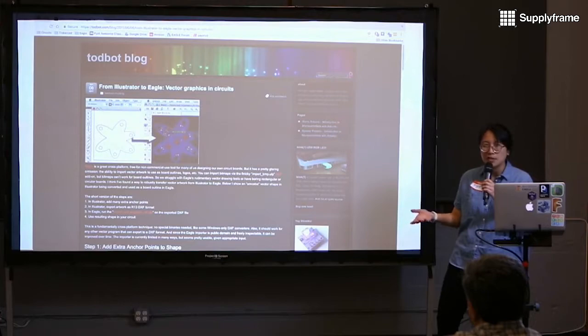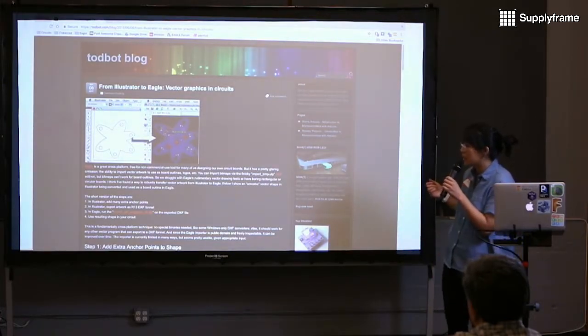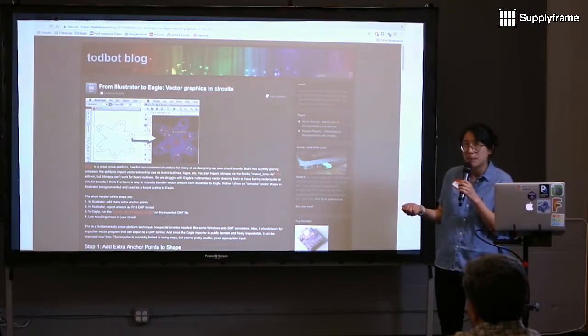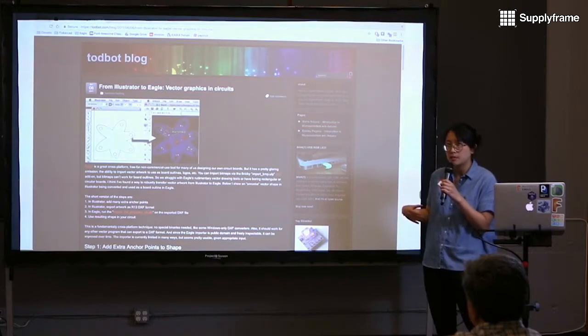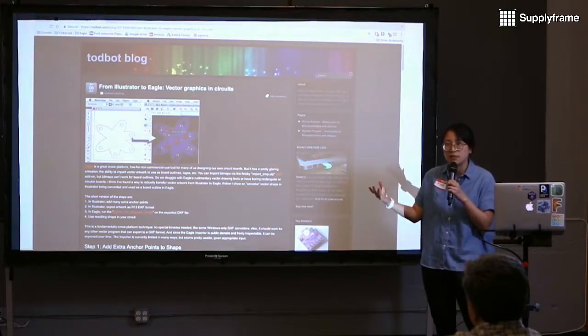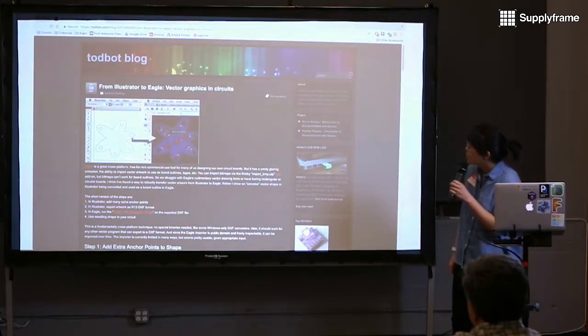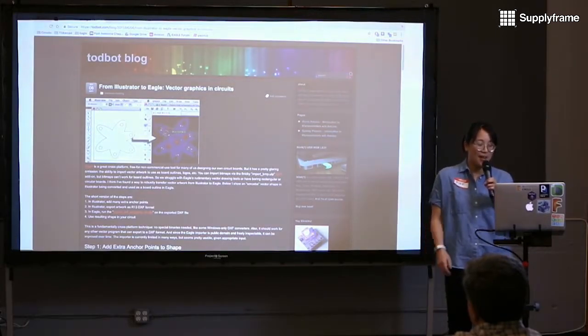For example, you can use a ULP to create a bill of materials. But this particular ULP was to take DXFs that you might export from an application like Illustrator and then import it into Eagle so you can get your board outline and use graphics software that has a lot more capabilities for designing more organic shapes. This ULP was called Import Dxf Polygons.